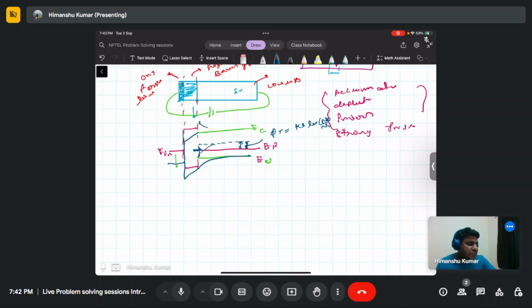That is known as the inversion layer. The surface potential psi f being 2 times phi f is the boundary for the inversion layer.